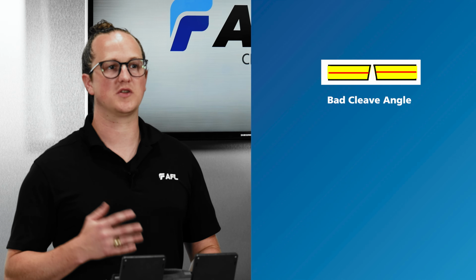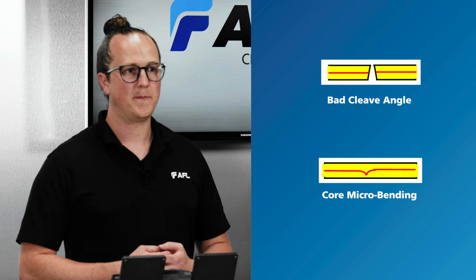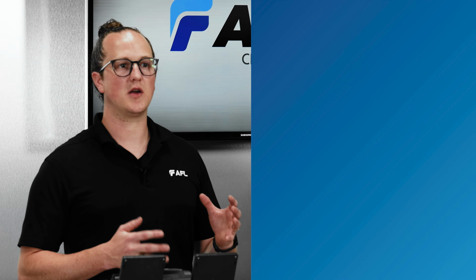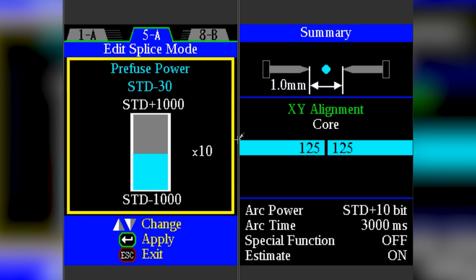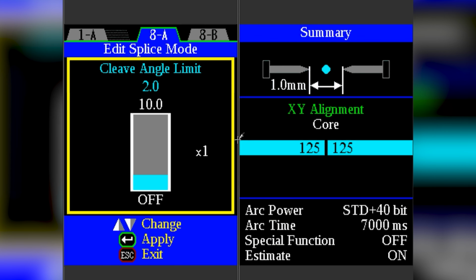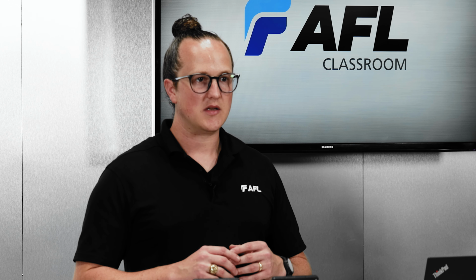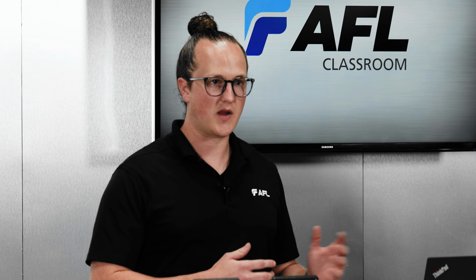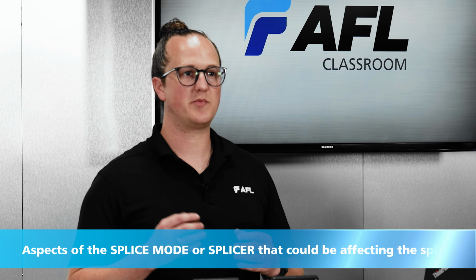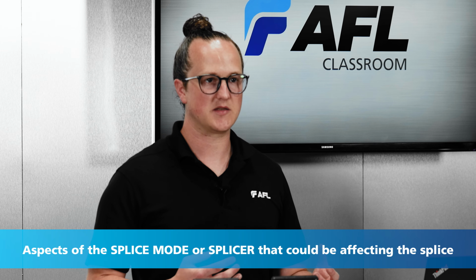When fibers with large cleave angles are spliced, you're likely to see some microbending of the core. This can be mitigated by either using a longer prefuse and main arc time, or by tightening the cleave angle alarm threshold in the splice mode. So now that we've gone over the fiber-related conditions, a splice mode condition, on the other hand, refers to a parameter in the splice mode or a physical aspect of the splicer that could be affecting the splice.